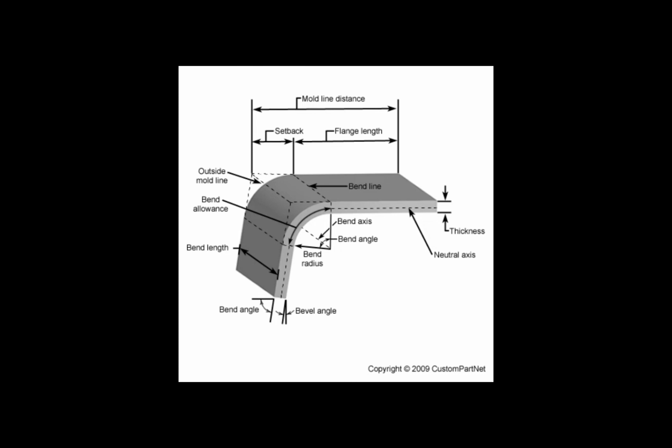When hand forming a piece of sheet metal that has a concave curve, should the forming be started in the center of the curve or at its edges? Edges and work towards the center. What are the proper dimensions for the shop head of a rivet? Shop head is the squish part, 1.5 times the diameter in width, and half times the diameter in height, after bucking.